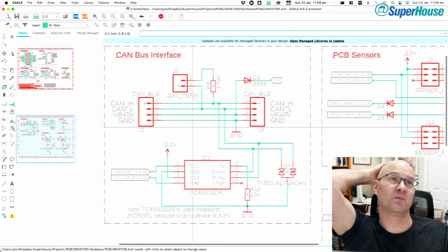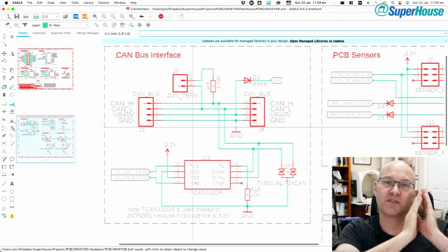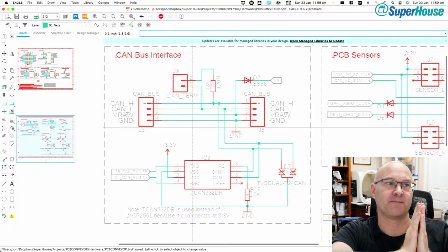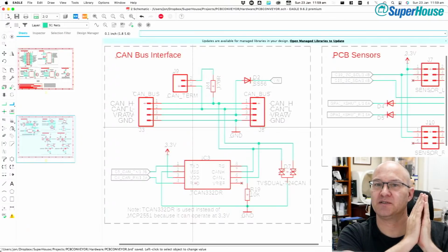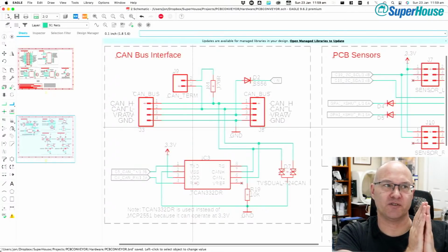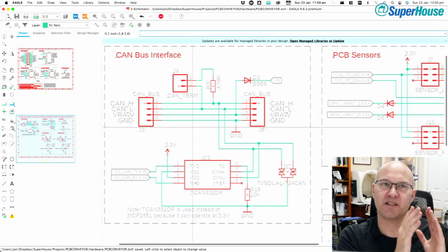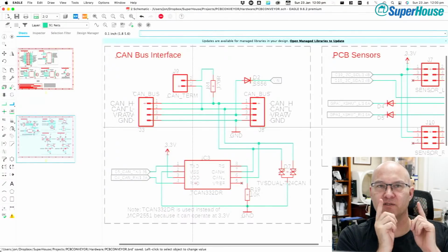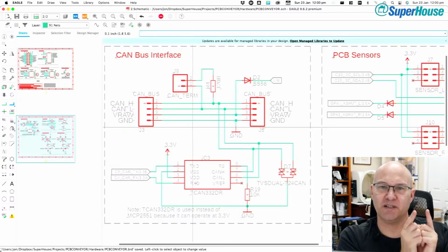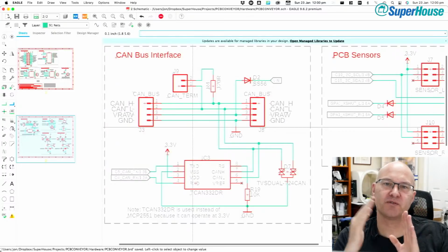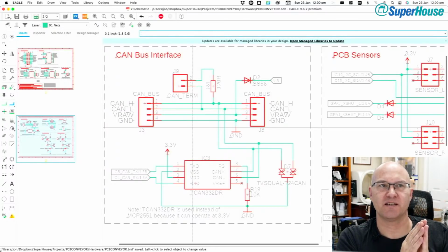Switching, one of the things that I've had problems with in the past is that anytime you want to switch power and you want to increase your current capacity by putting things in parallel, you can have issues. It can be, for example, say you're putting two relays in parallel to switch a load because you want to run through both of the contacts.